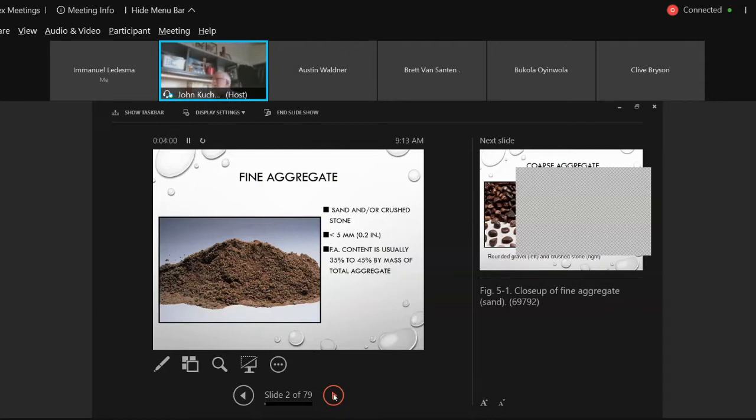And again, these specifications are CSA A23.1. Okay, remember, 0.1 are the specs, 0.2 are the test methods. So a lot of times you'll see something specified under A23.1 because it's pertaining to a specification, not a test procedure.